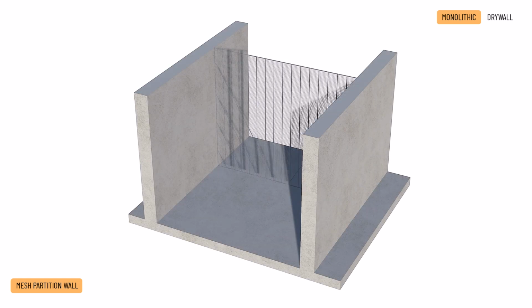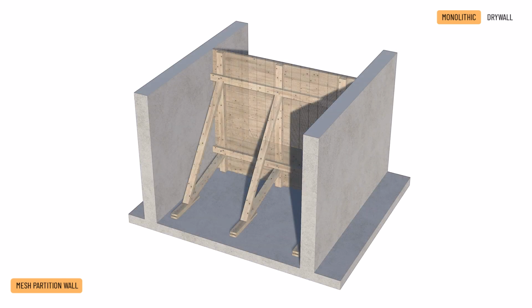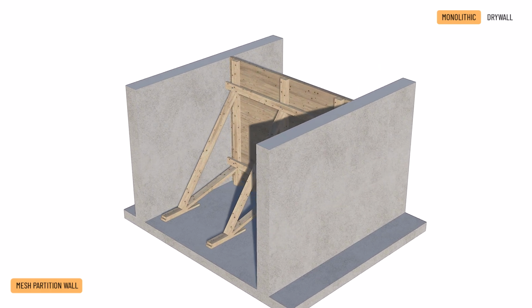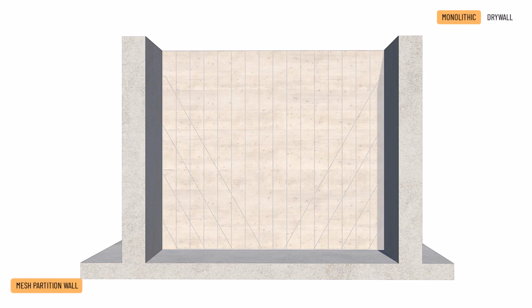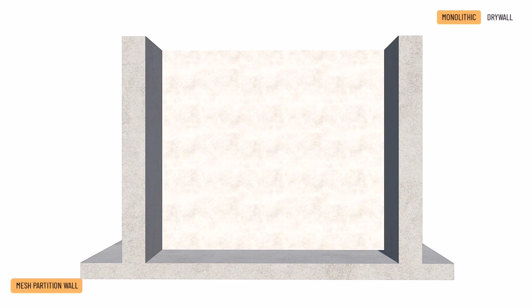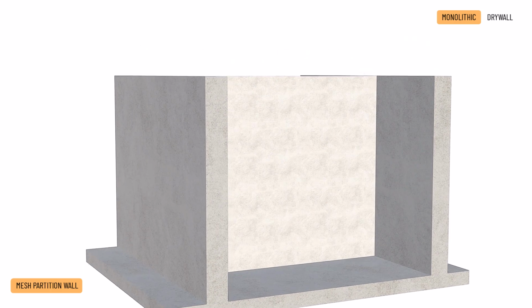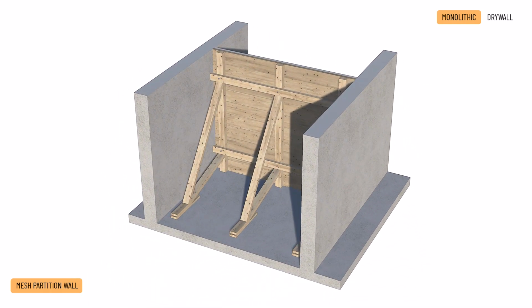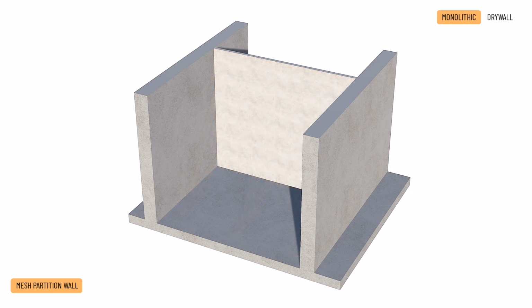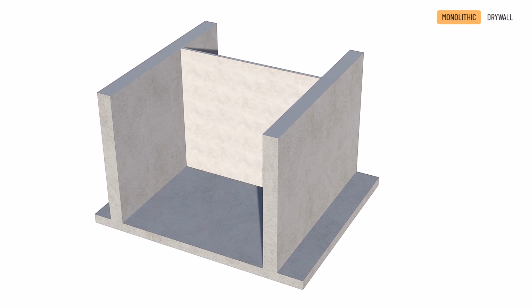Behind the supporting layer, a single-sided formwork is built with a 5-10 cm thick layer of gypsum or cement plaster applied to it by hand or machine. Gypsum plaster is a mixture of gypsum, lime, sand and adhesive, while cement plaster is a mixture of cement, sand and slag. After smoothing the surface, the formwork is removed and you have your partition wall.